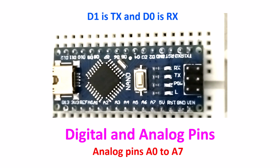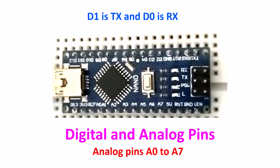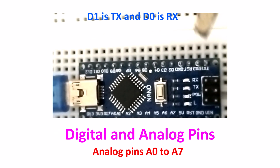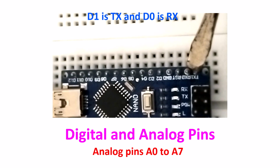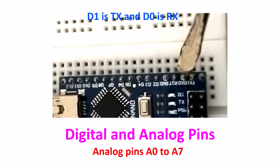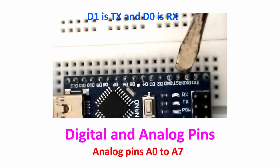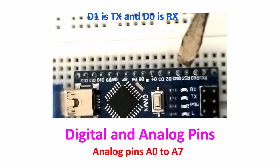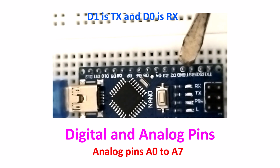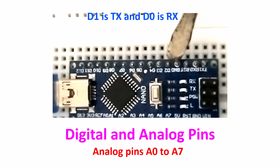Let's have a look at the pins here. There are various types of pins. These are TX and RX pins. RX pin is the input to the serial port. TX pin is the output from the serial port. RST is the reset. And GND is ground.